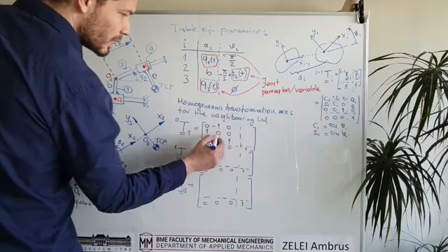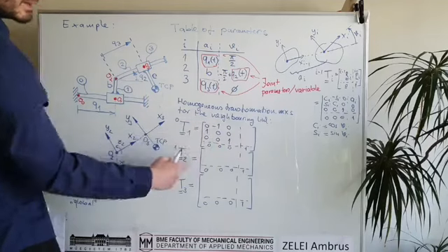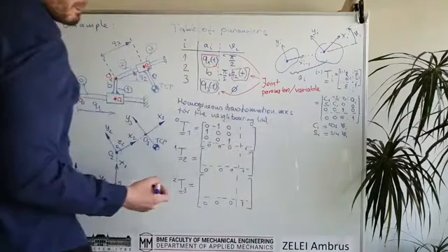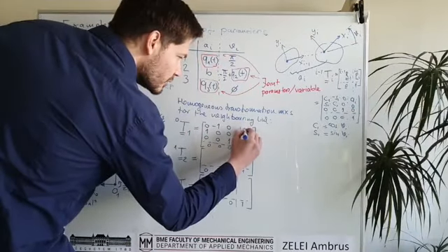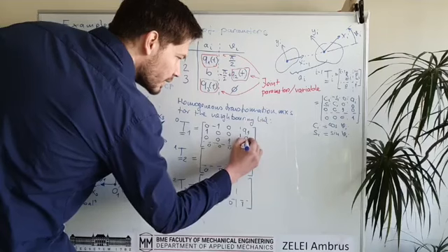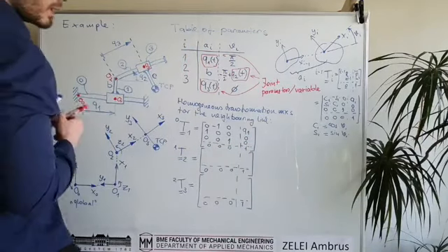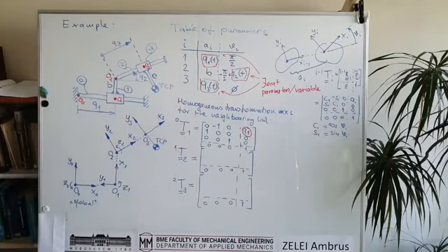So this is the rotational part for the first transformation, which is a 90 degrees rotation. And there is also a translation, which is basically our first joint coordinate q1. And we can show our joint variables again with red. Okay, so this is the joint variable, which is important.